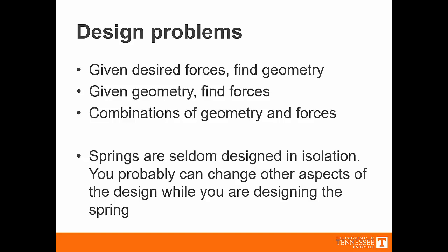Now, one of the nice things about spring design, especially in contrast to some of the other elements we looked at: when we looked at bearings, we said that bearings are typically designed very downstream of the rest of the design process. So normally, by the time you got to designing a bearing, you were pretty limited in the choices you could make. Springs are not that way. Typically, they're higher up in the design. And so that means, although it's very difficult to get an exact match for what your initial problem asks for, you probably have some room to push back as a designer and say, well, I can't give you 10 pounds, I can give you 10.2 pounds. Is that sufficient? And work through it that way.